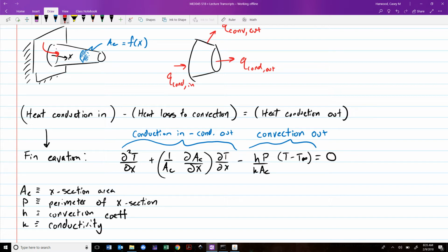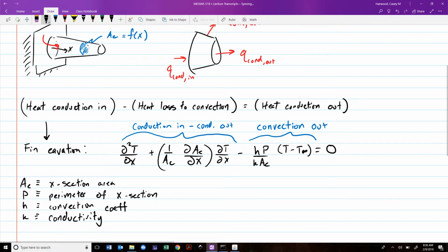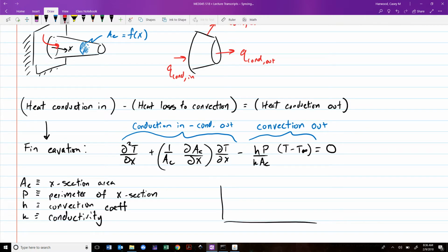Previously, when we did one-dimensional heat conduction, the temperature between two points would vary linearly, if we were talking about Cartesian coordinates. In cases like this, however, because some of that thermal energy is being shed out the sides of our surface as it conducts down the length of the fin, we can take an educated guess that rather than being linear, the temperature distribution is going to look something like this. It's going to be this sublinear behavior. So that's where we left off last time.